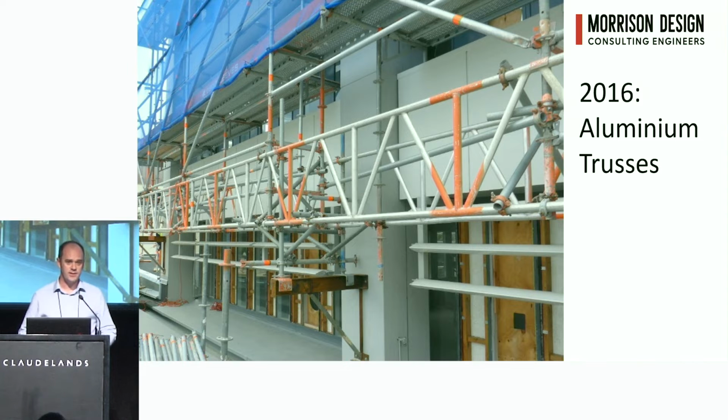This building in Wellington is fairly typical with a low-rise podium, and then the building carries on up with a tower. And what we usually do for a building like this is we would attach brackets onto the columns, as you can see in the photo here. We have something spanning between those brackets, and then we build up with a scaffold off that. The brackets are usually attached to the building either with mechanical or chemical anchors.